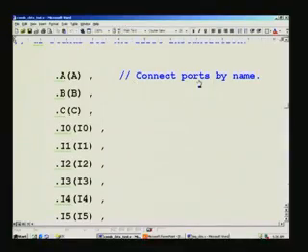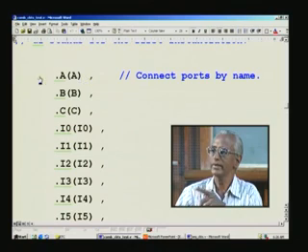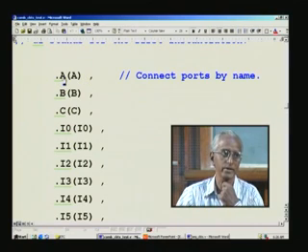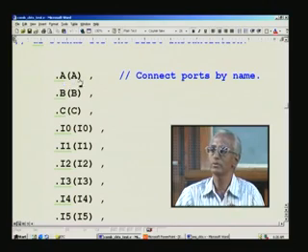So, the way to do this is what is called connect ports by name, right. How you connect the name is you use a dot here, and these two need not be the same. This means within brackets you are implying the A signal is within this test bench. Are you very clear about this? What is covered within brackets is within the test bench, not in the design, whereas this is the nomenclature adopted in the design. So, that is how you tie between the various permutation combinations.